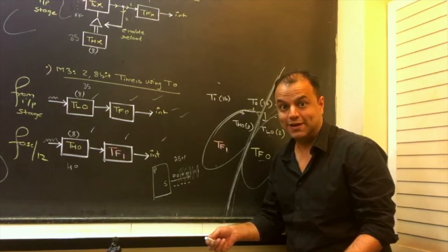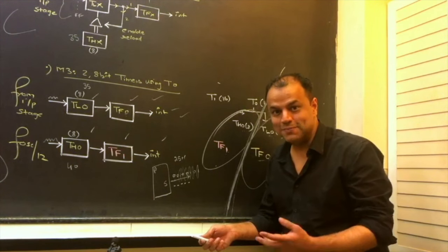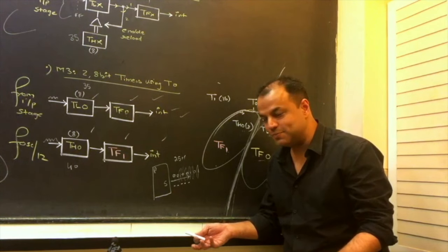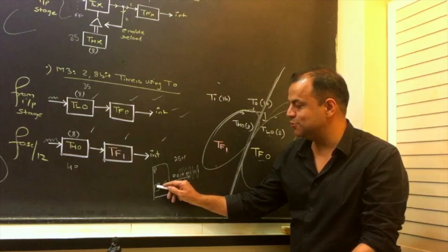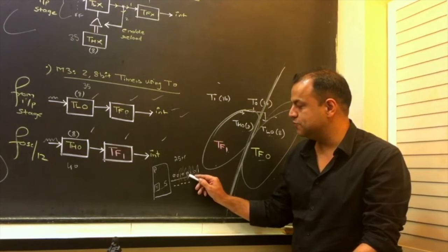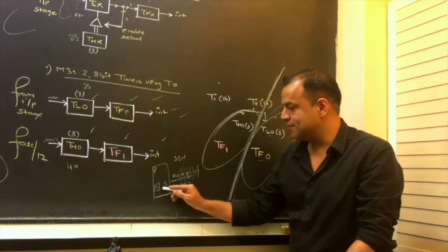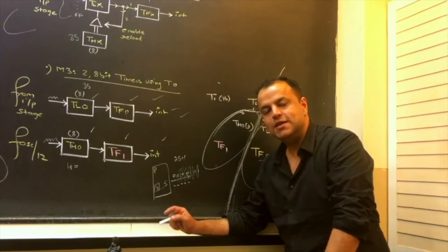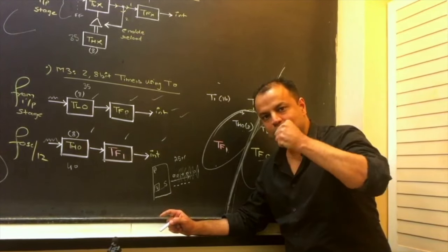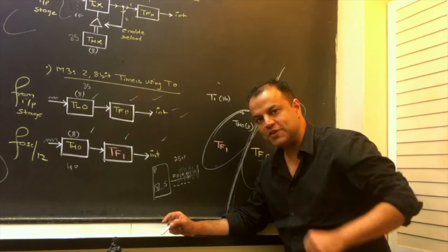Come on, please answer that, okay? We've been spending 1.5 hours on this. Please answer. Timers, delays are produced by timers. So what do you understand? When you do serial communication, you need a timer to produce the delay after every bit. The timer that is engaged in serial communication is timer 1. This is fixed. Serial port has internal connection with timer 1. Timer 1 is a personal timer of the serial port.